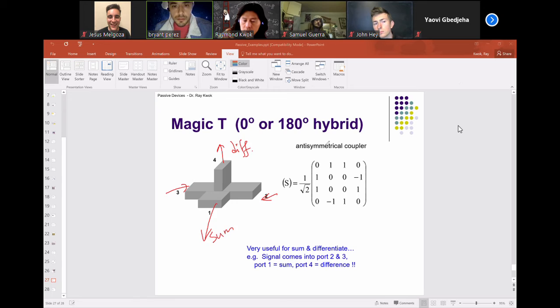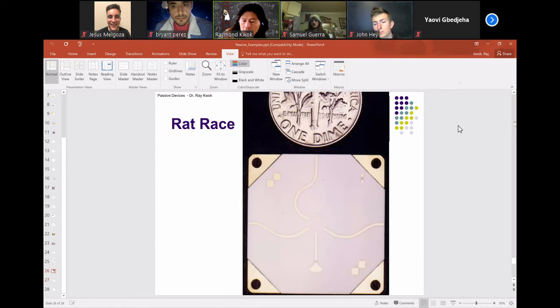Yes. Yeah, that one. See that little dark speck, that little dark area right before you get to the fan? Is that the 50 ohms? Yes. Okay. This is what I was talking about. This type of substrate circuit has a resistive layer underneath the gold. So when I etch off the gold here, I etch off the gold and the resistance. Here I only etch off the gold, and so it exposes the resistive layer. So that becomes a resistor, instead of physically putting another resistor there.